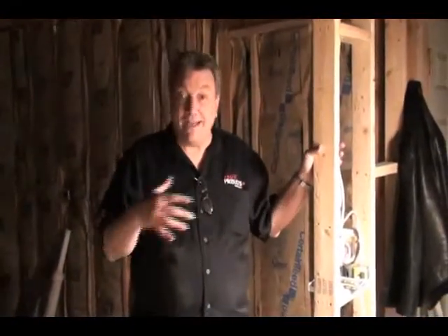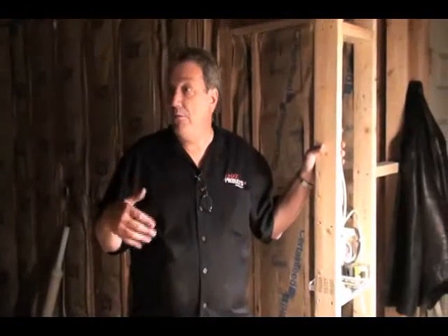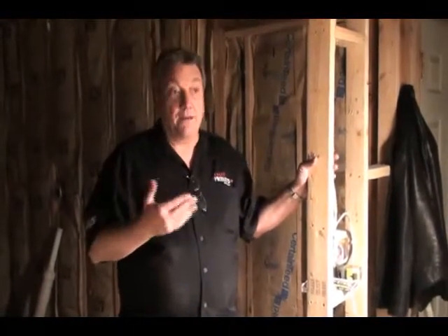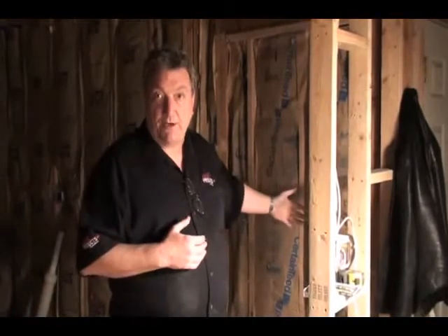Okay, we showed you already how the estimate could be created from the customer's own numbers. Now we're at the house, and at studs, as you can see, but we're going to measure the studs because in this case we might be doing cabinets also. If we're doing cabinets also, we'd like to know where the plumbing's at, where all the stud locations are. All we'll have to do is offset this for the thickness of the drywall, and in this particular case, won't have to come back to measure it again because it's going to be tile backsplashes in this particular case.